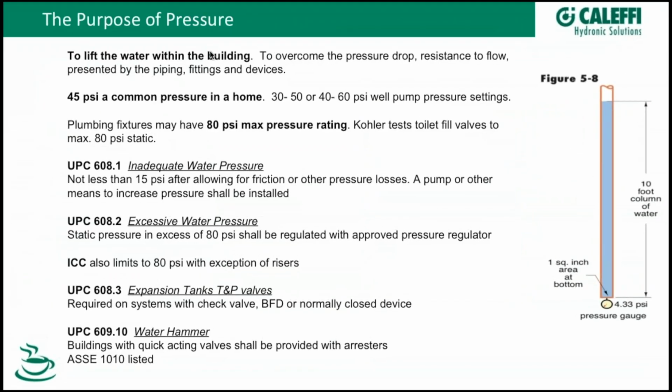So what we're going to talk about is pressure today, and for the purpose of this webinar, I define pressure as the exertion of a force upon a fluid. Basically, we use pressure in the system to lift the water, the static pressure. I'll show you some graphs as we go along, to get the pressure into the building up to the highest point in the building. And also when faucets or taps are flowing, we've got to have enough pressure to overcome the resistance in all the piping and fittings.